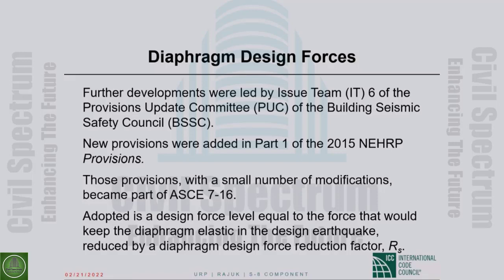Now that I'm going through the questions, I see there is a lot of confusion between the collector elements in a diaphragm and beams. They are getting confused about whether beams can be used as collectors or not. Absolutely. Quite often collectors are beams, but they don't have to be beams. They can be just a bunch of reinforcing bars that are entirely within the slab.